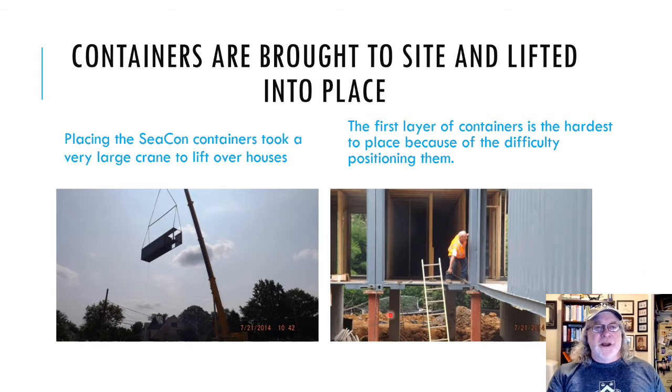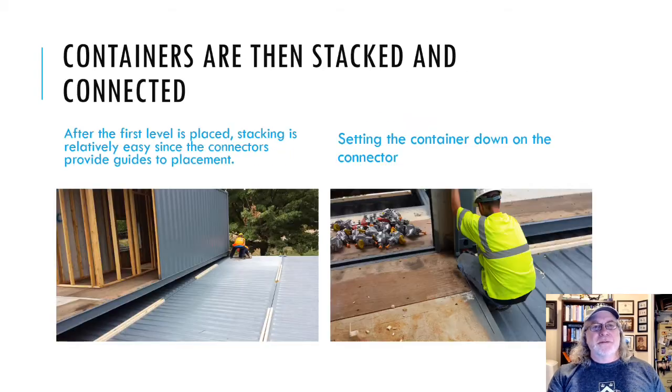And then positioning them in place in the first level is a pain. So the guy's prying here with a steel bar. That has to be done to get them in position. See how I've got these real thick plates that are oversized? I did that on purpose so you could slide these around a bit to get them in place so you wouldn't be threading a needle.